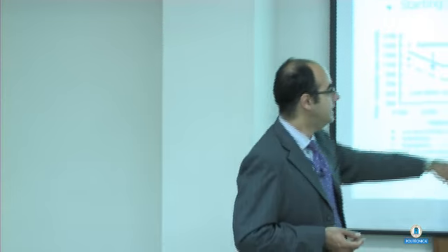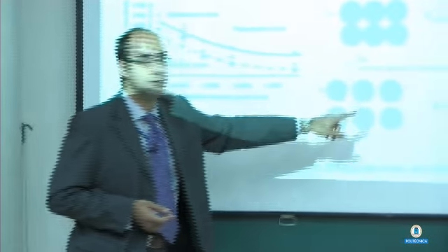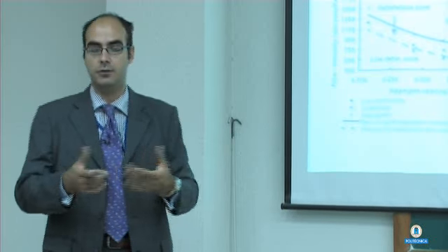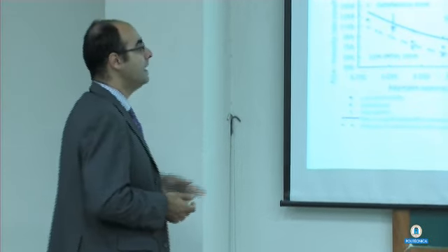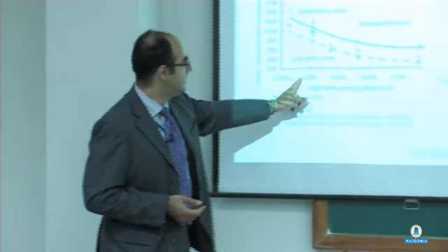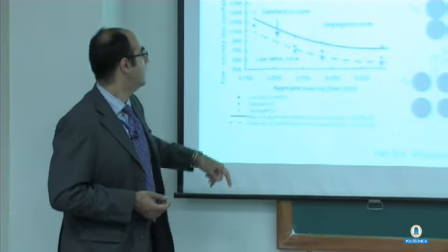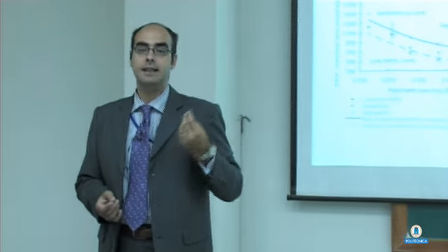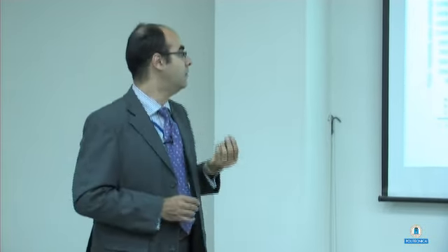And we assume this parameter here, which is the average spacing between the aggregates, which you can compute according to a simple geometrical formula. You can see here we have it on the x-axis. Here on the y-axis there is an indicator of the rheological behavior of the cement paste.